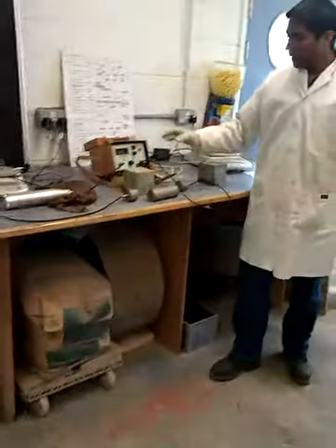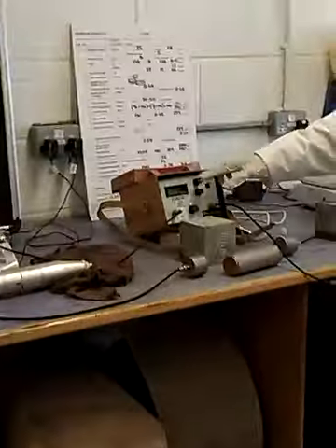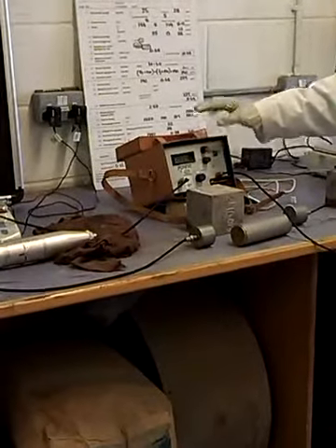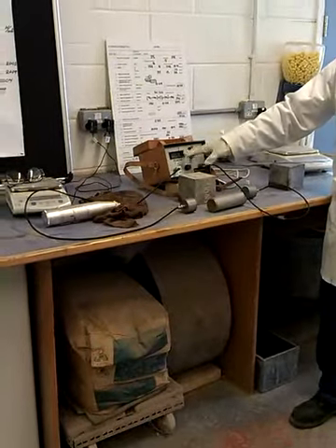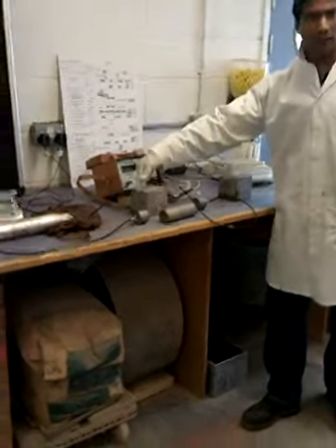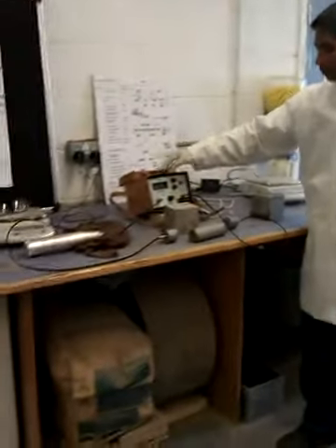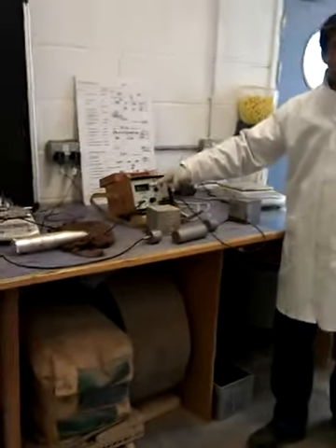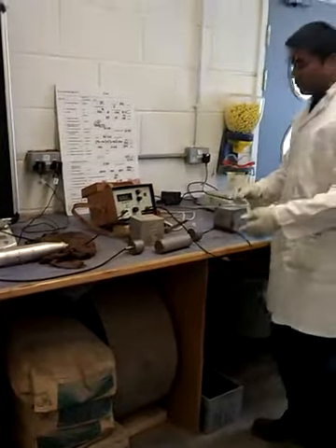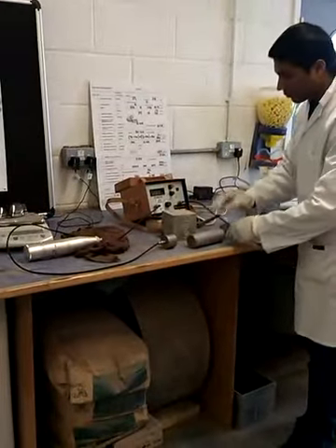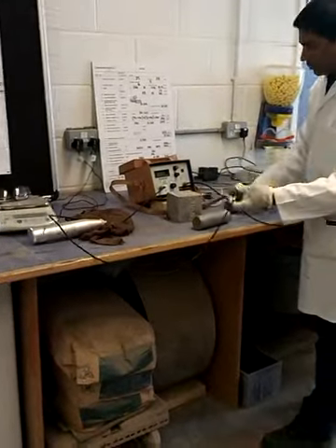Okay, once you calibrate, before you use it, it needs to be calibrated. For the calibration, you can see the numbers over here. That is detecting the time, how long it takes for the pulses to travel from one end to the other end, right? So that needs to be 25.5 microseconds. Okay, so for example, now over here, whether it will have 25.5 or not.